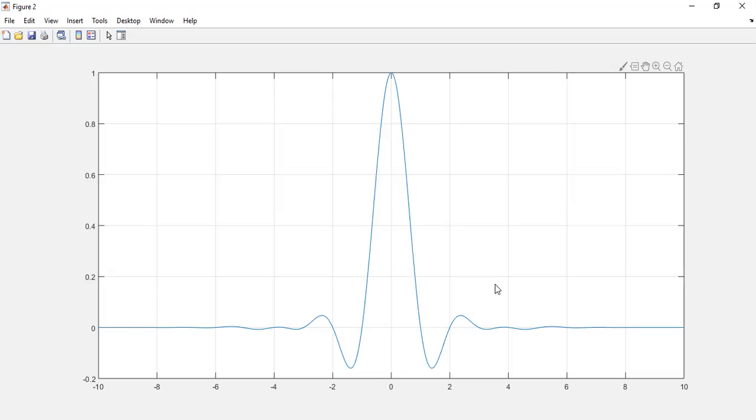This is still a logic of truncation, in the sense that you are limiting the data sequence in such a fashion that your bandwidth excess is being used, we know that, yet we are still using it, and we will have to truncate the data somewhere, because when we use it, there is always some possibility of intersymbol interference, but it remains in such a reduced amount that it becomes manageable. So this is the first aspect of intersymbol interference and the logic of raised cosine filters to completely, theoretically completely eliminate the logic of intersymbol interference.